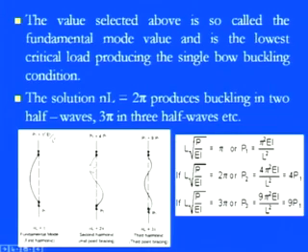At one, you see the perfect wavy form, and the other is a second form. Both the nodes and antinodes are being formed, and the orthogonality conditions are there in the different modes of buckling. Similarly, if we keep 3 pi equal to NL, then obviously P3 equals 9 pi square EI divided by L square, because now it is in terms of the square terms. So we have three different modes, the third harmonic terms.